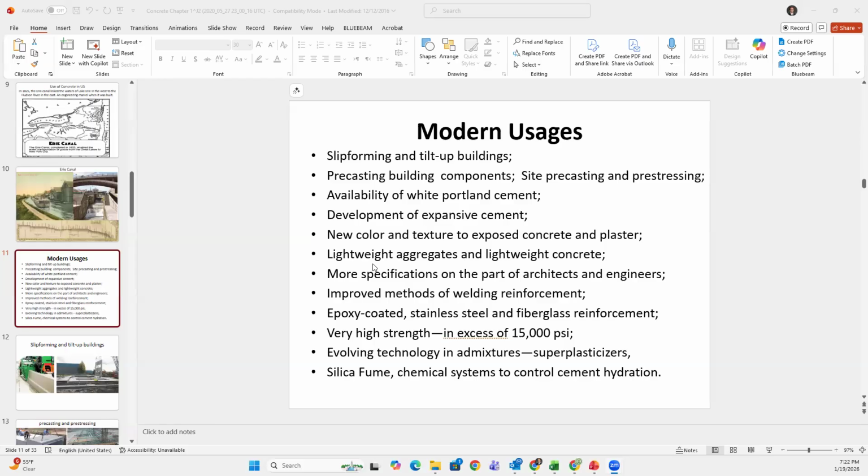And then when your building grows and becomes taller, let's say 3 or 4 story parking garages, you use the regular strong concrete. But if you have to build a very slender, ductile, high-rise building, then you use the lightweight concrete. And you heard the word ductile last week from me.